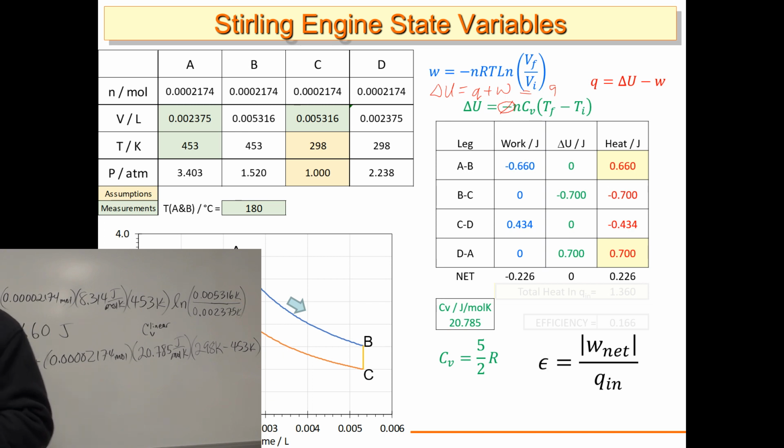And so that's not very much, okay? But again, it's per revolution. If you get 1,000 revolutions per minute, then you get a measurable amount of work out of it. And then the total heat in. This is where people make mistakes. They think that it's net work divided by net heat, which would always give 100% efficiency. Okay. But you have just the positive values here.